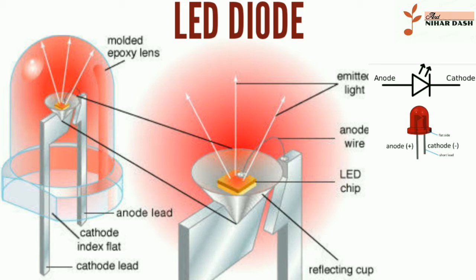A light emitting diode, LED, is a special type of p-n junction diode. The light emitting diode is specially doped and made of a special type of semiconductor. This diode can emit light when it is in the forward biased state. Aluminum indium gallium phosphide, AlInGaP, and indium gallium nitride, InGaN, are two of the most commonly used semiconductors for LED technologies. Older LED technologies used gallium arsenide phosphide, GaAsP, gallium phosphide, GaP, and aluminum gallium arsenide, AlGaAs.